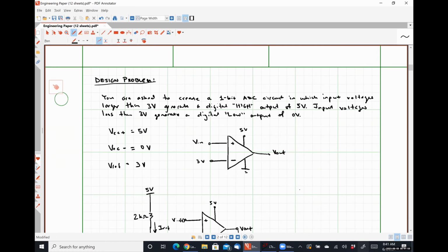That is why, if you hook your current meter up in parallel to a particular resistor or something like that, you wind up burning out your fuse. It's because all of the current is bypassing your element of interest and flowing through that very, very low resistance of the fuse, which burns it out. So that's why you measure voltages in parallel and measure current in series, because it's how the measurement tool is designed to operate.